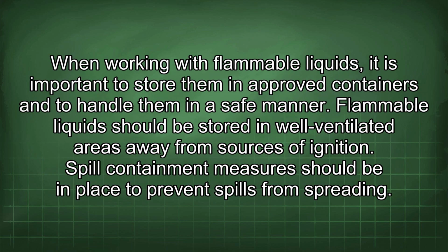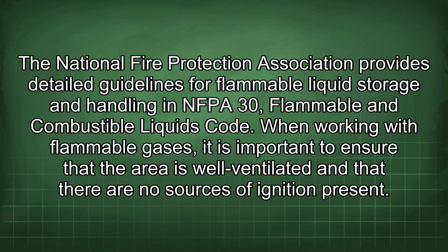When working with flammable liquids, it is important to store them in approved containers and to handle them in a safe manner. Flammable liquids should be stored in well-ventilated areas away from sources of ignition. Spill containment measures should be in place to prevent spills from spreading. The National Fire Protection Association provides detailed guidelines for flammable liquid storage and handling in NFPA 30, Flammable and Combustible Liquids Code.